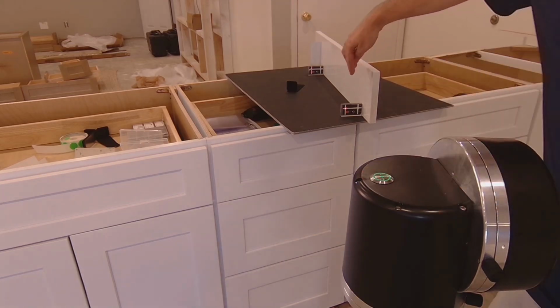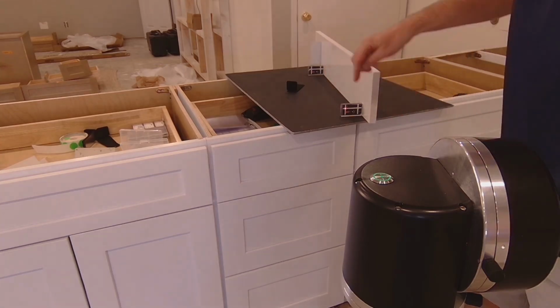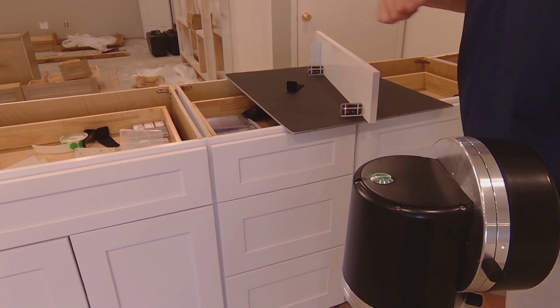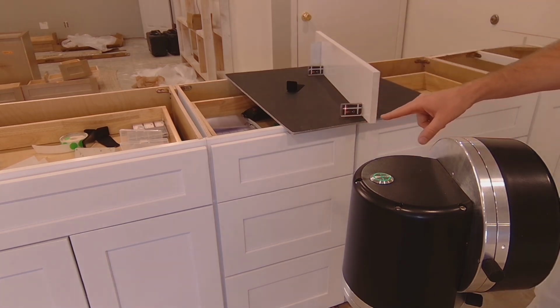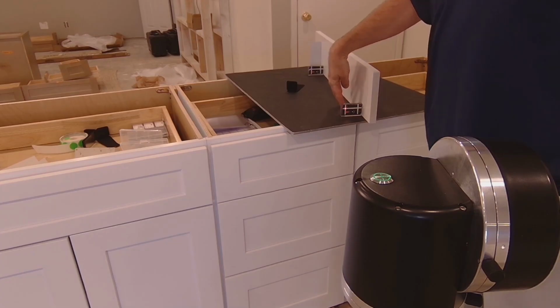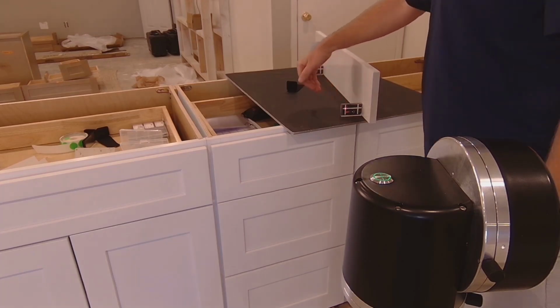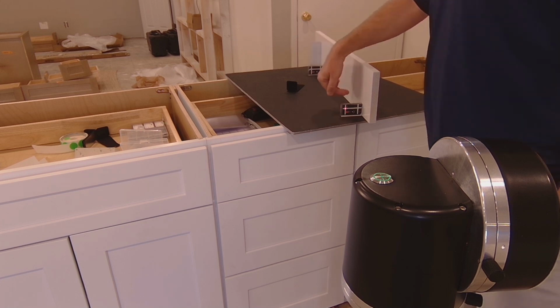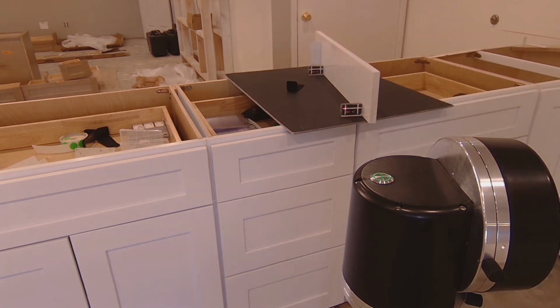This is a very clean way to get a measurement. And then I would offset this line 2 inches. I like to do this right away so I don't forget. Often I would shoot this in a different color as a visual reminder, so that I would offset this to this edge. Most often that's what we would see.